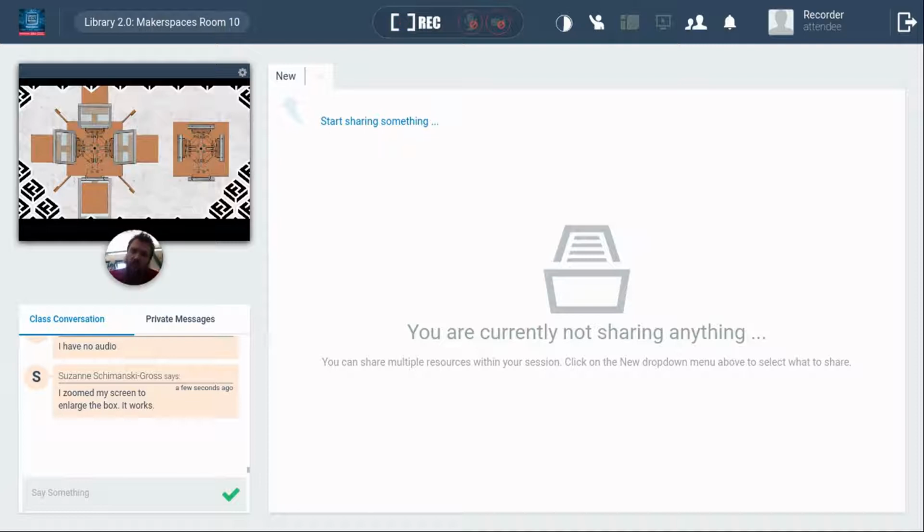We didn't build the press that's available online on DIYprintingplans.com directly. We looked at it and made some changes that made it more robust. So taking out a basic Lazy Susan and putting in pillow block bearings, and then adding detents so it clicks into place a little bit better, and some spring loading so that it wants to stay up and then clicks down and helps hold itself.